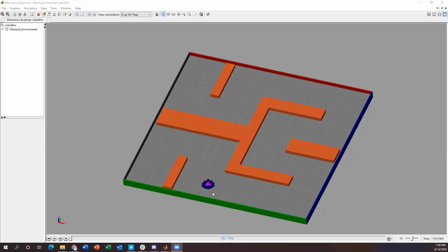What I've learned from this is that the more it turns, the more error there is, and the more it starts not going in the middle, because unless you have a gyroscope sensor, just using time measurements can be a little inaccurate, understandably. We're almost finished, and that's as far as I could get to. I couldn't get it to touch the wall over there, but that's as far as I could get it to do, just because, once again, it's measuring that wall and wants to turn back around.